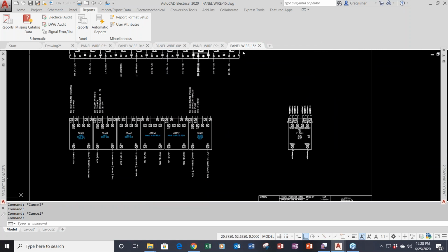Or you do it like I did here: create a second footprint symbol, and then add the correct attributes that it needs for the wiring annotation. So you can look at it two different ways. Keep one footprint symbol and play with the layers, or create a second footprint symbol in a secondary drawing, or however many drawings you want.